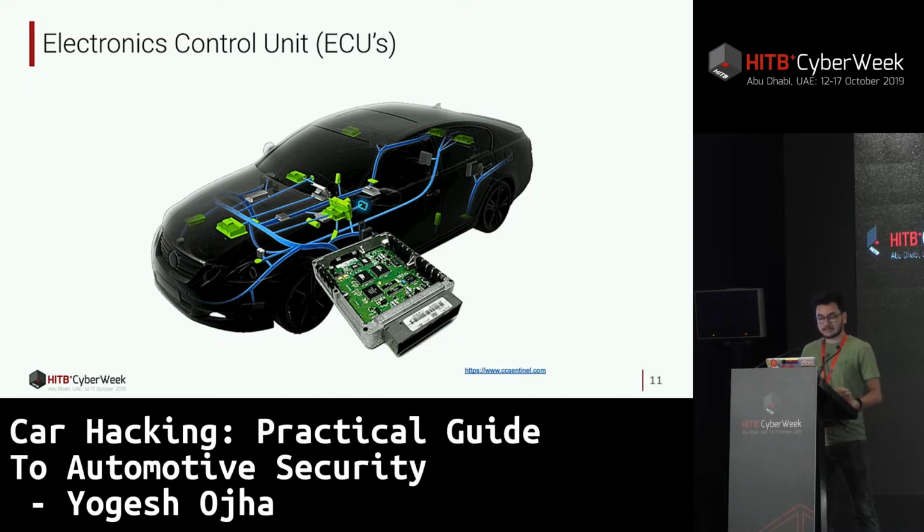An ECU is any controller that typically has a microcomputer inside it with a bunch of wires and peripherals, running a small algorithm in a closed loop and waiting for some input. Once the input is fed, it makes some decision based on that, and the output is in the actuating. It's an actuator, for mechanical components like moving the steering, engine combustion, and critical decisions like airbags and anti-braking systems. These generally have something called a closed loop. This is a scheme that monitors the output of a car system and controls the input. So it's not going to take any input that is not intended for it.